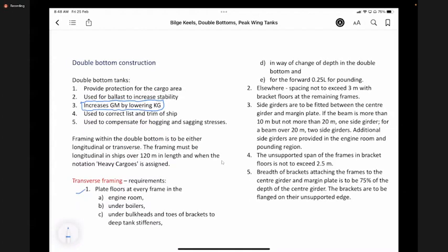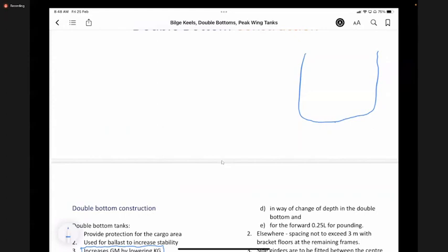Basically, in the ship, we have a few points. We have the K, that is the keel. And then we have the B. This B is the centroid of the underwater volume. We consider the buoyancy force to be acting upwards from this center of the entire ship. And then we have the M, which is called the metacenter. Do you know what metacenter is?